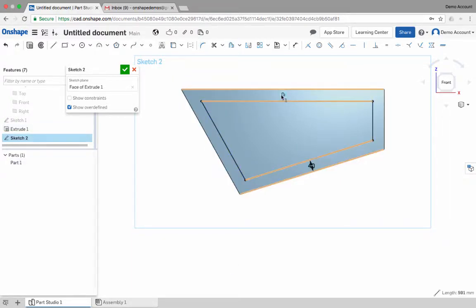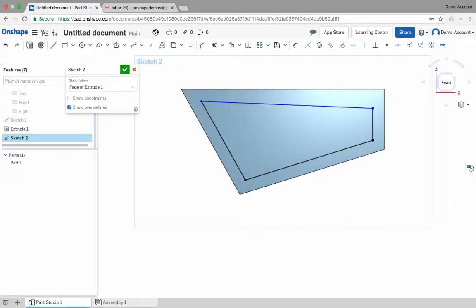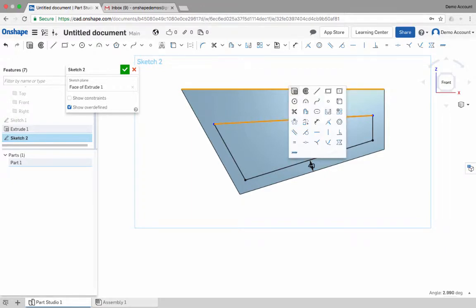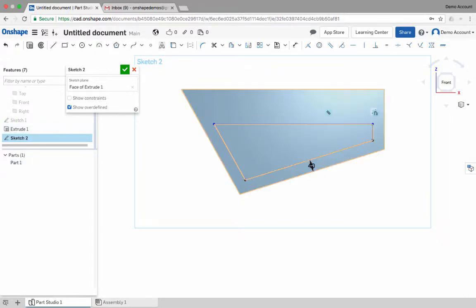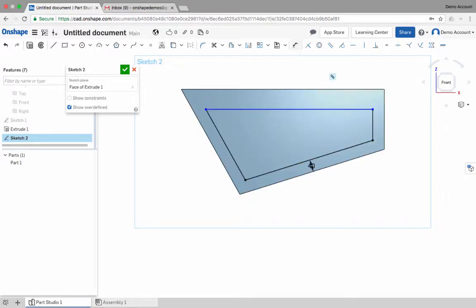This top one, quite often with these toolboxes, you'll have a rope rail. So I want that rope rail to be a little bit different to 40. So what I'll do is I'll go in and I'll delete that offset constraint off that top line. The opening is always going to be parallel to the top face, so I'll use parallel, which is B, which is probably a bit of a funny one if you can remember B for parallel. Or you can just use the S key and pick up your parallel there. So now we've got a parallel constraint. We'll put that one on there.